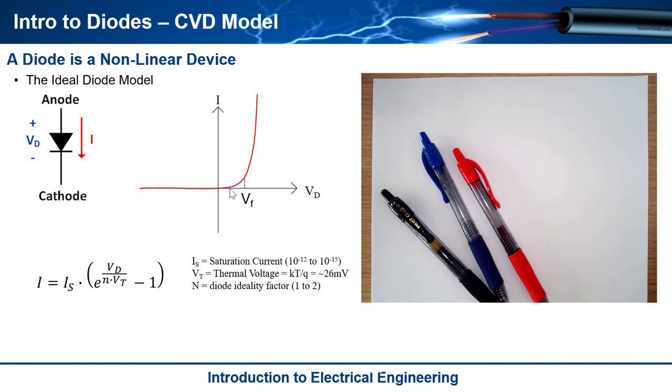So it's actually an exponential ramp though. If you look at this, it has very low current, and then once it gets above this forward voltage, it increases drastically. And you notice that once it turns on, the resistance of the diode is 0. It looks like a wire, so you can't develop any more voltage across it, and the current just goes way up exponentially, and you can't really develop any more forward voltage across this.